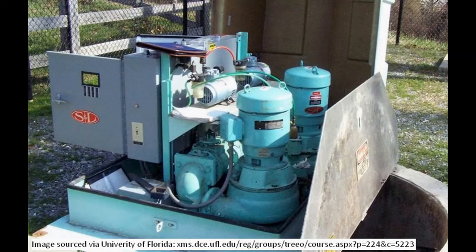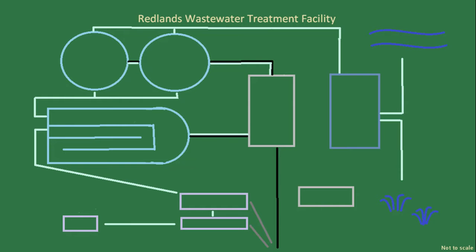Lifting stations are strategically positioned. Their number is minimized by installing them at key areas, places of low elevation where smaller pipes have already converged into larger ones. Through this network of pipes, the area's wastewater arrives at the treatment plant. Immediately after it arrives, wastewater enters the primary treatment phase.